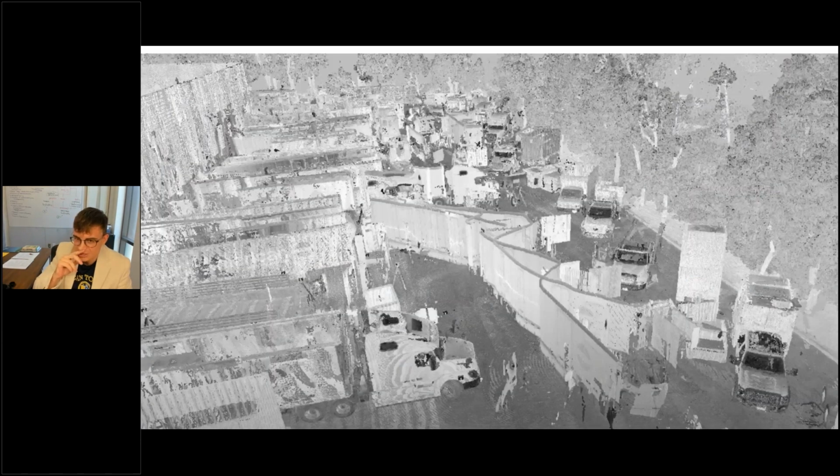Incidental noise is just irrelevant stuff. Clutter or objects that are in the scan, but they don't benefit you or the client. Clean it if it's getting in the way, otherwise try not to waste your time. And don't delete this kind of noise, hide it instead, because you never know if it will be useful downstream. I'll also define transient noise. It's a kind of incidental noise. This is moving clutter, like people moving around, cars moving around, and so on.